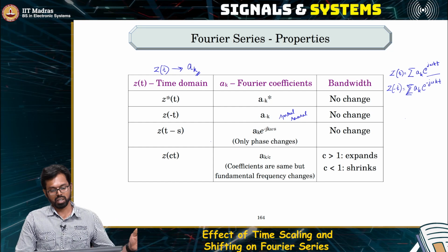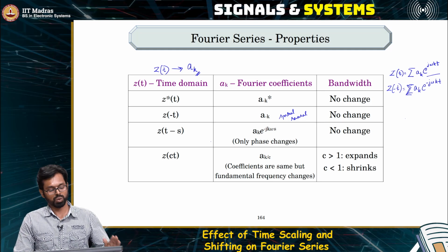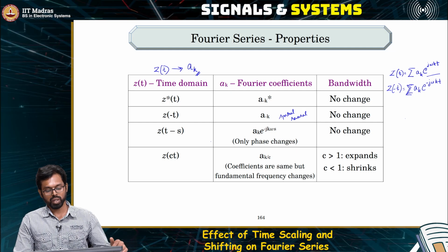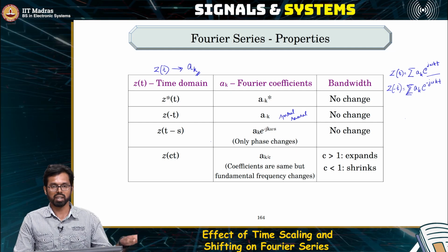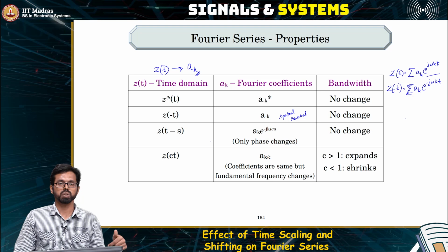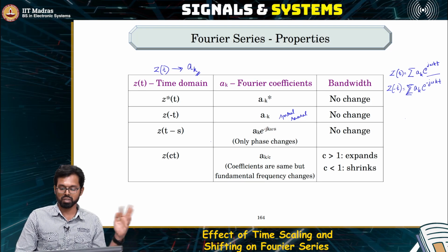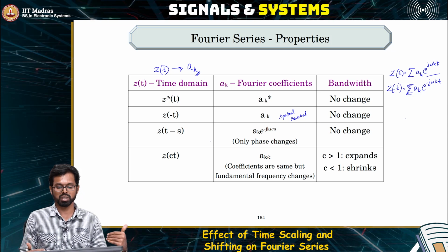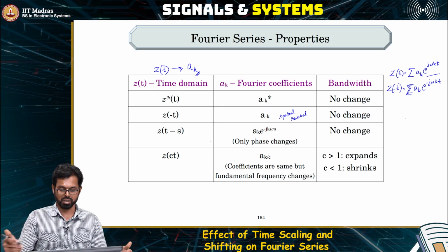So the frequency component should remain exactly the same. But when it has earlier started from left to right, now we have flipped from right to left. Which means something which was going clockwise because of time reversal is now going anti-clockwise. You reversed time, right? So positive frequencies become negative, negative frequencies become positive. That's exactly what we saw. So the intuition completely follows the analysis.